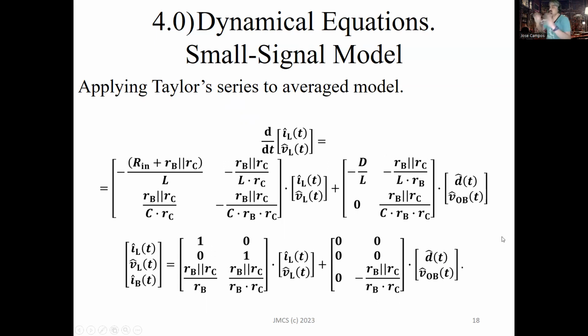So now we are able, for example, to convert this into a state space form. As you can see here, we have the state equation, and here we have the output equation. Taking this information, you can now convert this system into the Laplace domain and finally get the transfer function of the system. Or, for example, you can take these equations and apply them in the state space domain, and apply, for example, a quadratic regulator in order to get a controller for regulating the system.